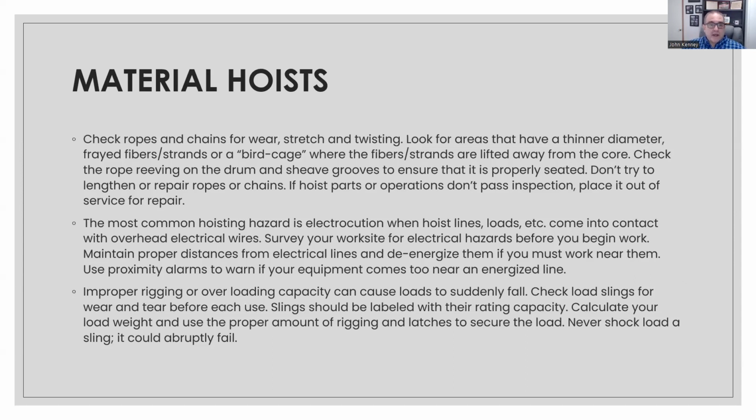So improper rigging and overloading capacity can cause loads to suddenly fall. So always check and make sure that you're not lifting a capacity higher than whatever your slings are rated for. Make sure there are no cuts, tears, etc. And you want to calculate that load weight and use the proper amount of rigging and latches to secure it. So again, always do your homework up front, make sure you're doing it safely, and you're going to avoid injuries at the end.